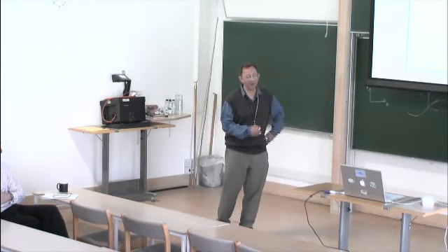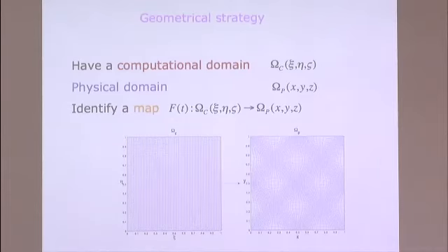And then I have a function f, which is a function of time, which maps that domain into the physical domain. Here's the physical domain, and this is where your equations sit. So this is where your Navier-Stokes equations or the Euler equations or whatever you want to do sit in that physical domain, and all your equations are posed in this domain. And then we get a mesh in this domain, which is the image of the completely uniform mesh in the computational domain. And just to make notation easy, I will use Greek letters for anything computational, and I shall use Roman letters for anything physical.